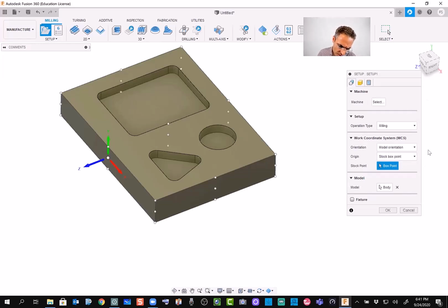So how do we do that? See on this box that we have, it says, where do you want your origin? You see the word origin here? I open it up and I say I like to select a point. It asks me, okay, please tell me which point, and I just click one of these corners. Now this is my origin. Also, I need to tell my tool what is X, what is Y.